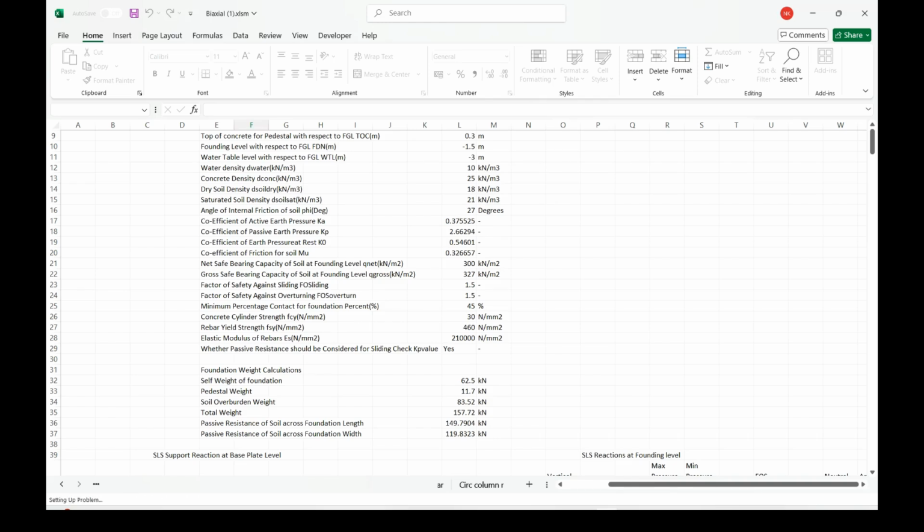We calculate the reinforcement. We check the foundation for the one-way shear and two-way shear. We check the adequacy of the reinforcement which we are proposing as a trial, to indicate whether the foundation reinforcement and thickness are adequate for all the criteria like punching, one-way shear and flexure.